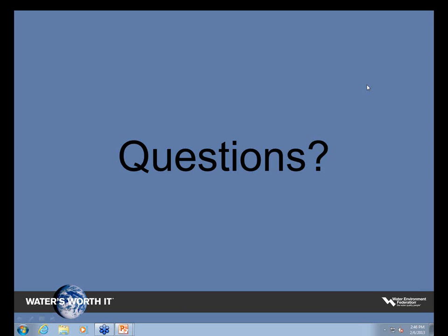Right, and I think that's a good lead into the next question. We talk about all the advances that we've had in UV technology over recent years, and now we're seeing systems validated well below 35% UV transmittance. And so I've got a question from someone who's a regulatory process reviewer asking, what do we do? We get requests for UV doses less than the 30 based on MS2, and also for effluent UV transmittance less than 65%. What's a regulator to do? I'm going to throw that to you, Paul.